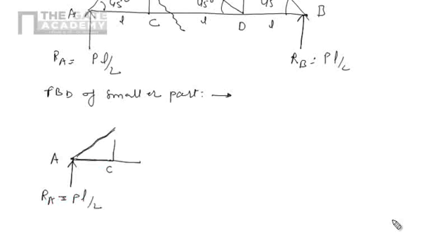Now we have to show the forces in the cut members. According to our assumption, all the forces will be tensile, so away from the joint, away from the joint, away from the joint. This is FA, this is FCE, this is FCD. So these are the members we have shown in this free body diagram.